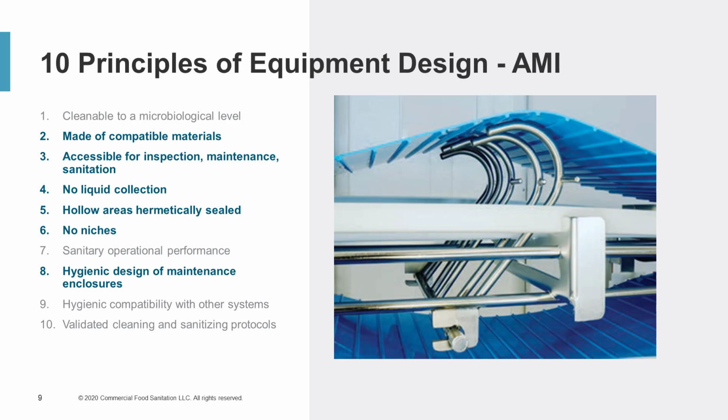Starting with number 2, considering chemicals that are used for sanitation, not only routine, but also periodically. Which leads us to, for instance, the choice of material for framework being stainless steel. And principle number 3, the biggest one, accessibility. Designing in access to clean, either through direct access or through disassembly.